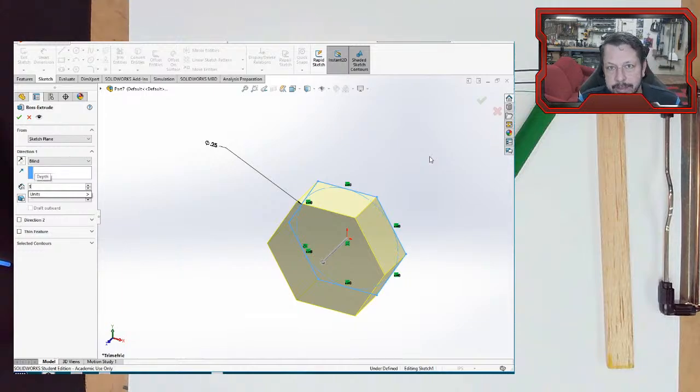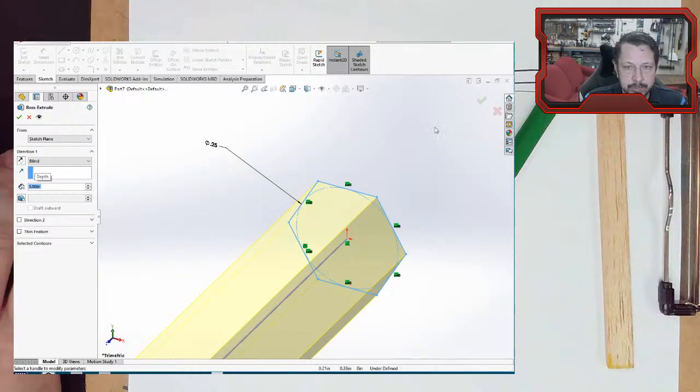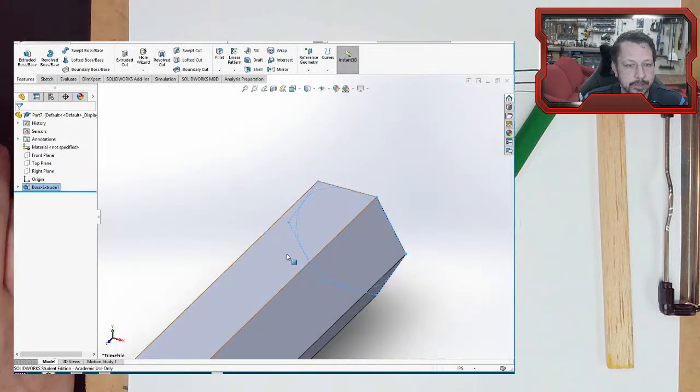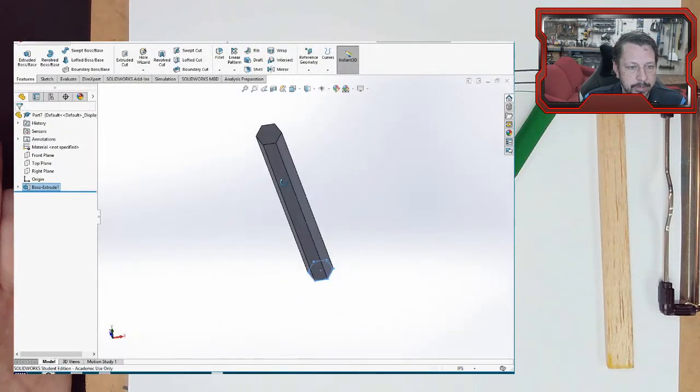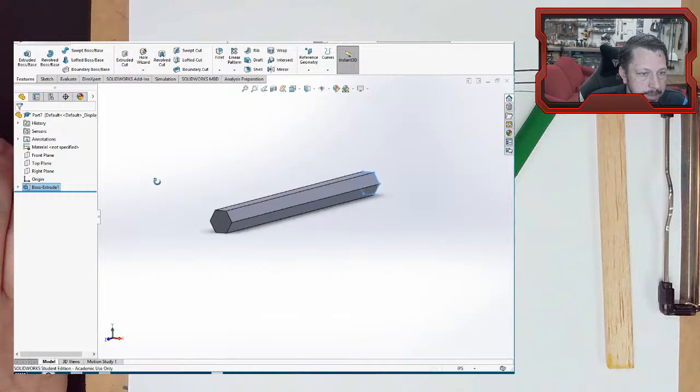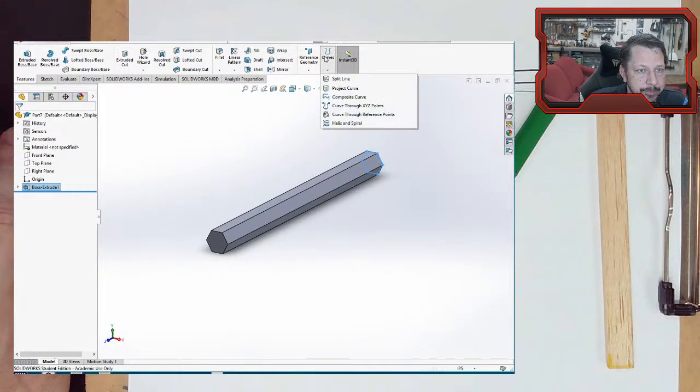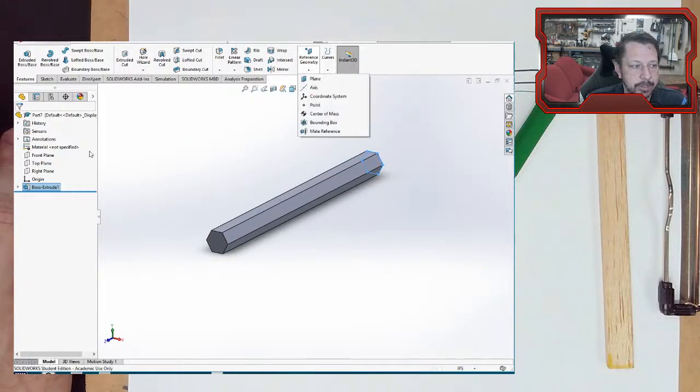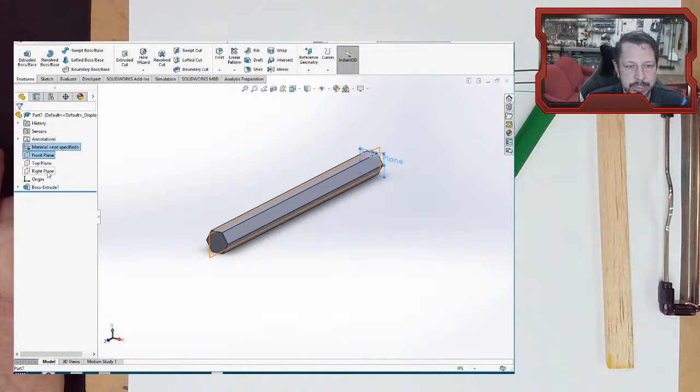They're generally a little bit wider than the sample that you're using. So my sample was 1 inch wide. I'll make these 3 inches wide. I'm going to put a split line on the bottom of these pieces to help with alignment also. So I don't have to make a plane. The right plane is already right through the center of this since I made it at the origin. So I don't have to make a new plane. I'll use that one. So split line.